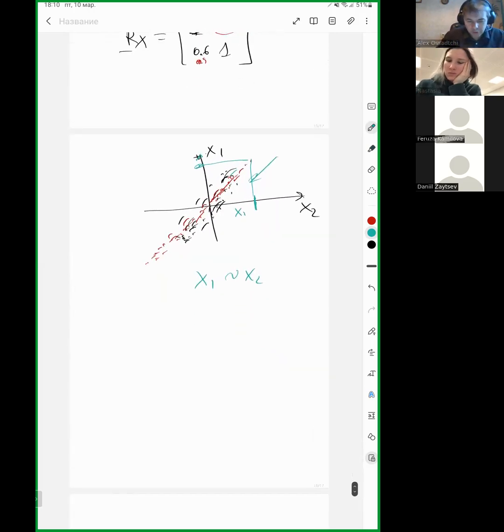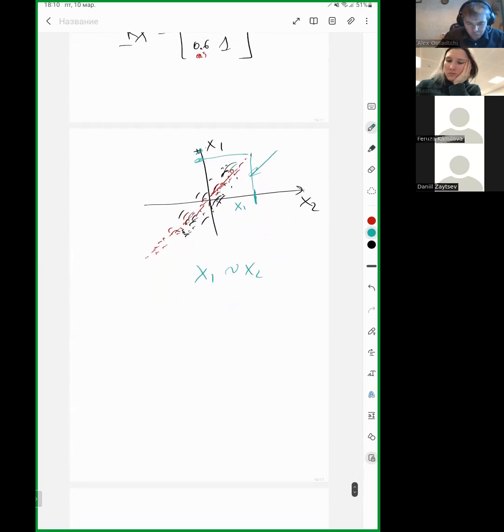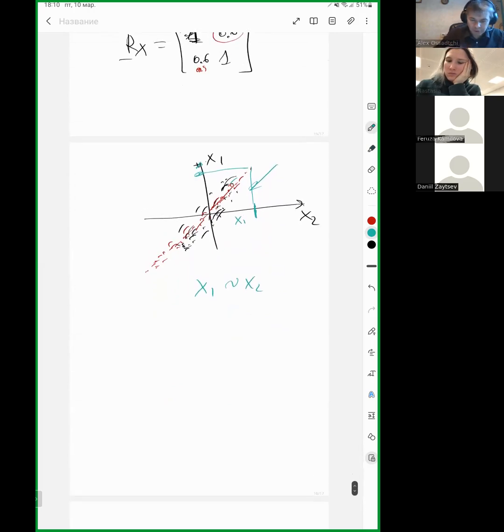So there is such a thing called whitening. What you do with whitening is simply turn this picture into a spherical picture again, but you do it mathematically, artificially, virtually. You place yourself in a space where the interference is spatially even, with no spatial preference at all. In this new space, it becomes very clear how to tune to a particular source.